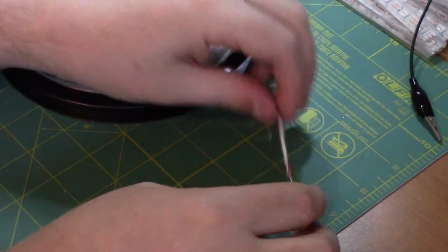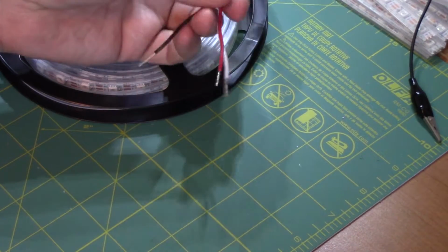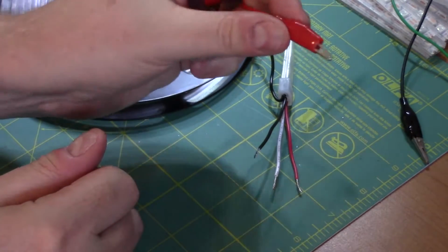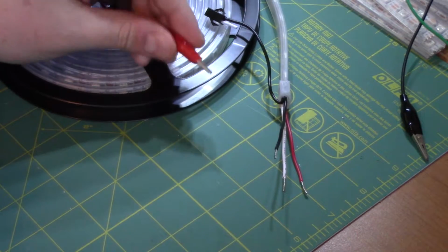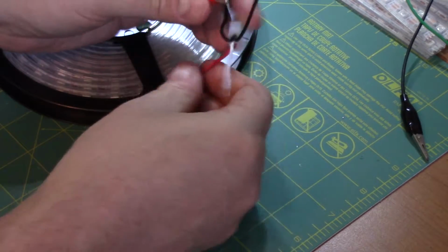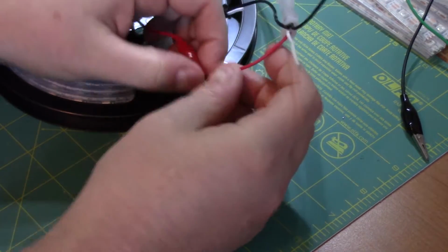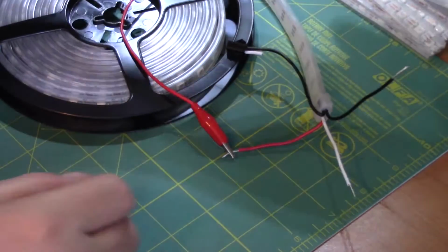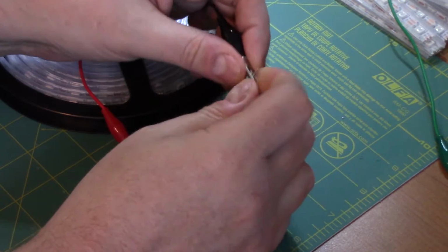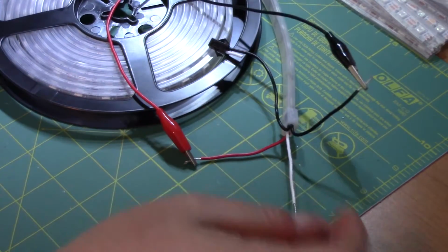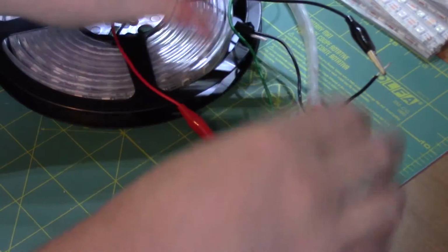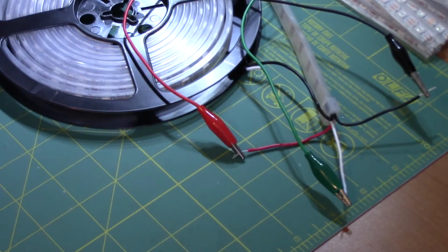And then to hook this up to the Arduino, the easiest thing I found is using these alligator clip wires. Little alligator clips on the end. Very easy to attach here. So just clip some on the end of each of the wires. Make sure they're kept separate so nothing's touching. So I've got my red one here. Clip it on the end of the red one. I've got a black one. Attach that to the black, to the ground. And then I'm going to use a green one here for my data. Attach that to data. And again, make sure none of these things are touching. Spread them apart if you have to.